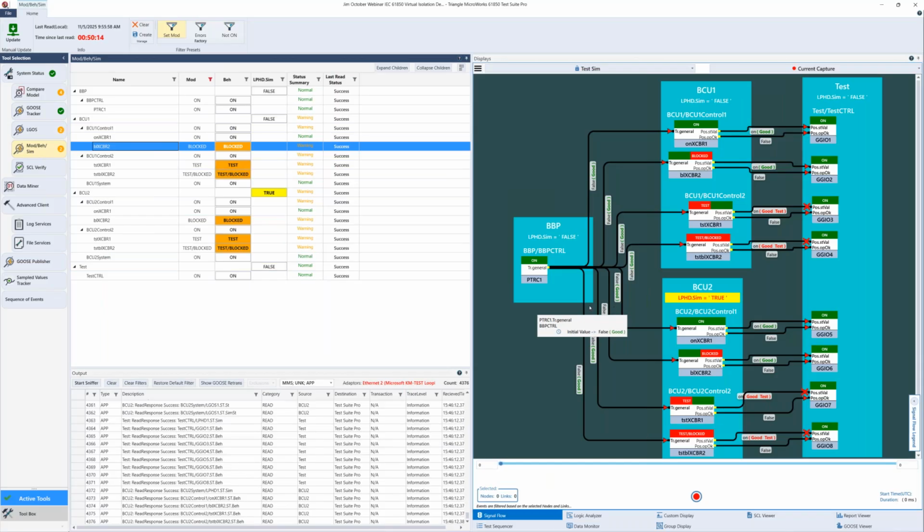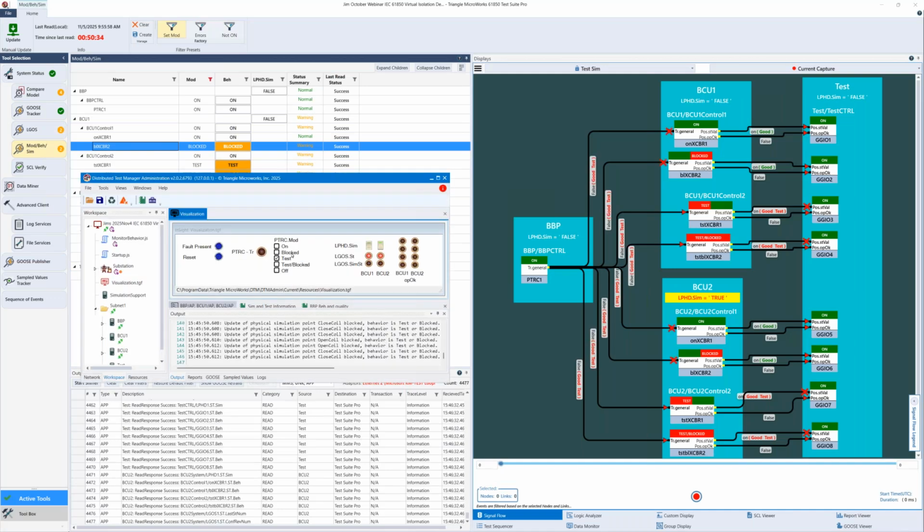Now let's see the operation when this device would be in test mode. So you want to test a couple of devices or lots of functions, but not necessarily everything should operate. So that's why we now put this as well in test mode. And you can do that down here. You can put this in mode test here. You see also here, it indicates now that this is in test. On signal flow, where you see all the signals, you see the quality now is test. It's still good, so it's valid, but it has the test quality bit in addition set.